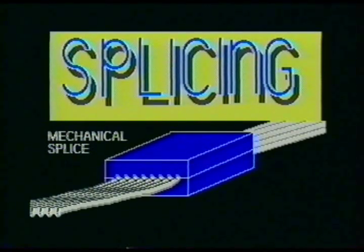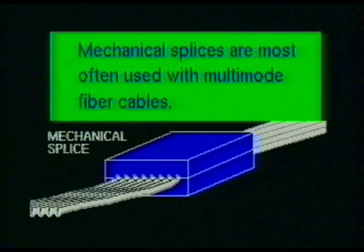It was mentioned earlier that splices can also be made by gluing the fiber ends together. This also makes a permanent connection. However, the cable loss is somewhat higher. This form of splicing is often called mechanical splicing. Mechanical splicing is most often used with multimode fibers. The one major advantage of the mechanical splice is that it does not require expensive splicing equipment.